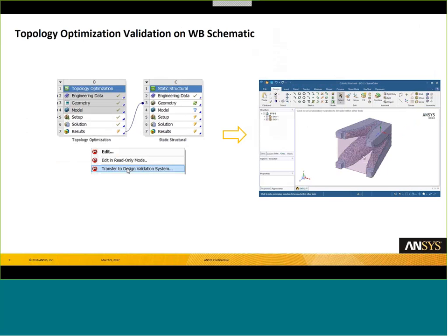Once here, you can recreate the geometry based on the type of manufacturing you might be doing, because topology optimization is also useful with traditional manufacturing, whether you're machining or casting. You do a lot more with additive, but it still is awesome for traditional manufacturing.